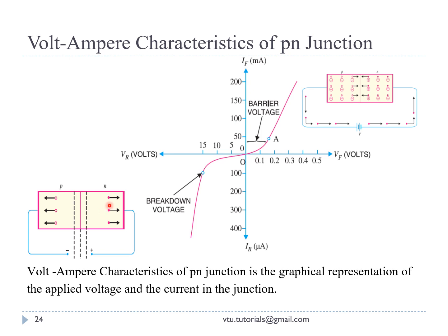If the reverse voltage is further increased continuously, the kinetic energy of the electrons may become high enough to knock out the electrons from the semiconductor atoms. At this stage, breakdown of the junction occurs, characterized by a sudden rise in the reverse current and a sudden fall in the barrier region resistance.